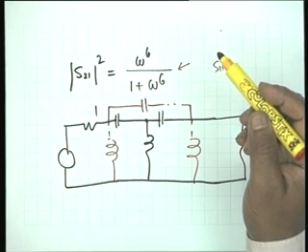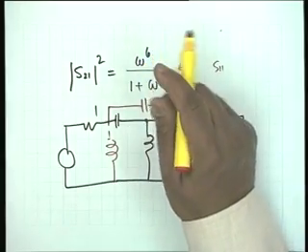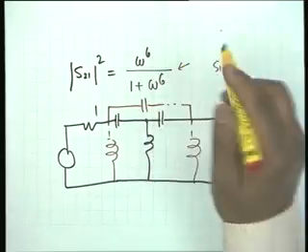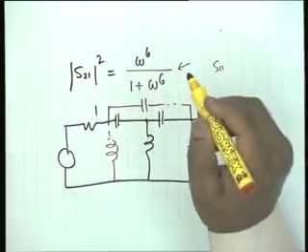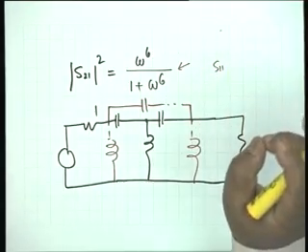Pardon me? We can't have 1.5 order. Say it again. We can't have 1.5 order. No, order is not determined by the numerator. Order is determined by the number of poles, the denominator. Could we have here instead of 6, could we have 3? Tell me why. It won't be real, sir, when we convert it to.